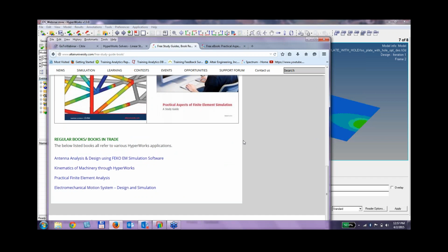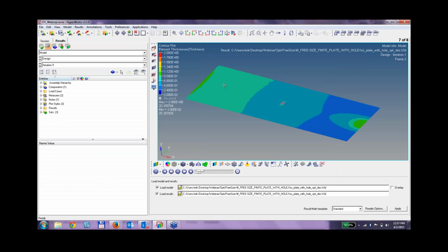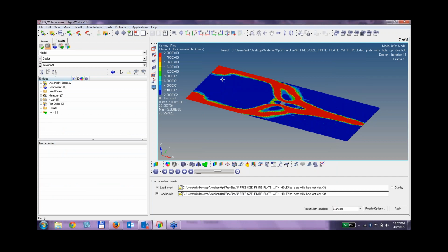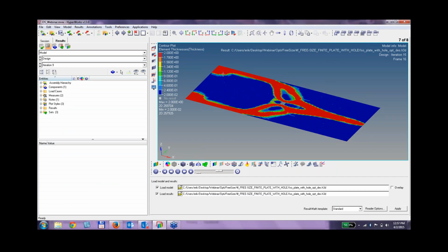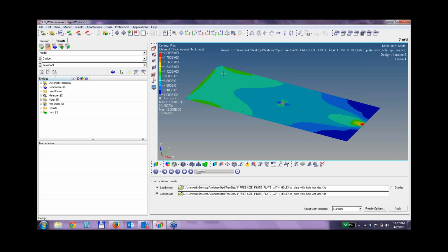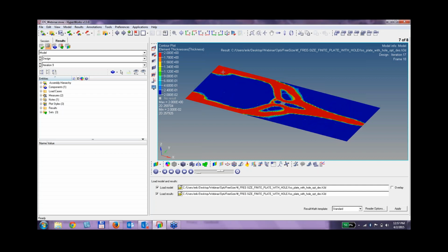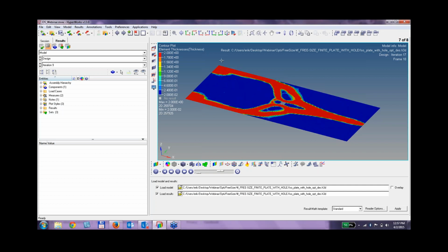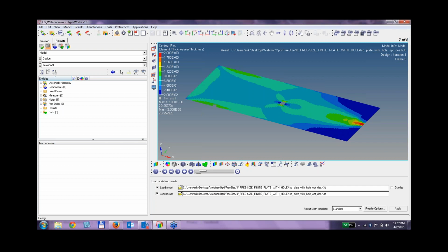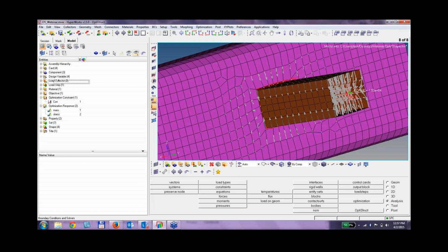No, you don't. So when you set up the analysis, when I model a part, I'm creating an FE representation of some sort of geometry. Then I apply properties to my elements. If they're shell elements, that will give them thickness. And then I apply a material in there. So my material, if I come back here to HyperMesh, if I come here to my material, you'll see my material has this rho value here, which is the mass density of the part.